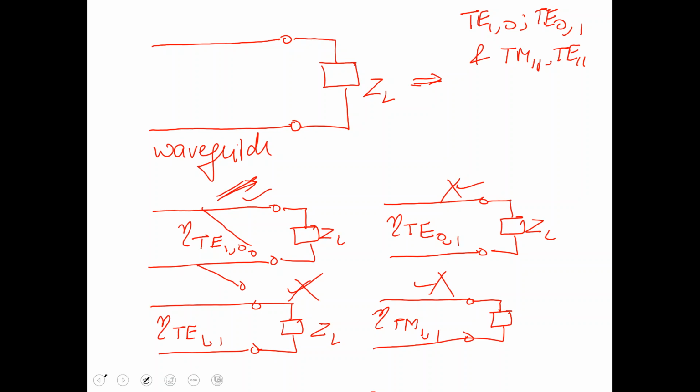So again, it tells you that for most applications we want a single mode solution, single mode waveguides. Or if we have a multiple mode waveguide, we have to design our excitation circuit such that only a single mode is excited well.